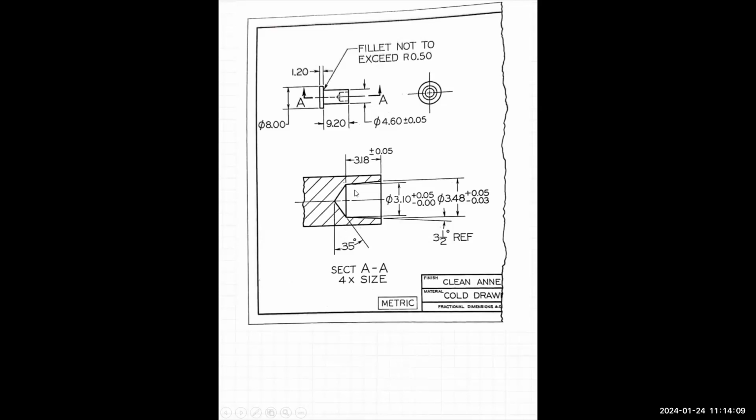So it's kind of just a partial though. They put the cut all the way through, but then they didn't show this piece. Really, if you cut it all the way through, they should have shown this piece. They probably had room to show the whole thing. Why not, right? But they were obviously just interested in this bevel hole thing. So that made it a lot easier to dimension, because you couldn't dimension anything up here. Those are all hidden lines. Now they're all visible, and we can dimension it. Make sense? All right, let's keep going.